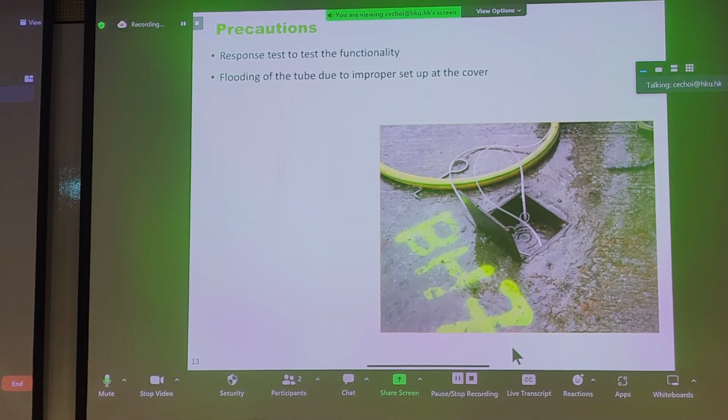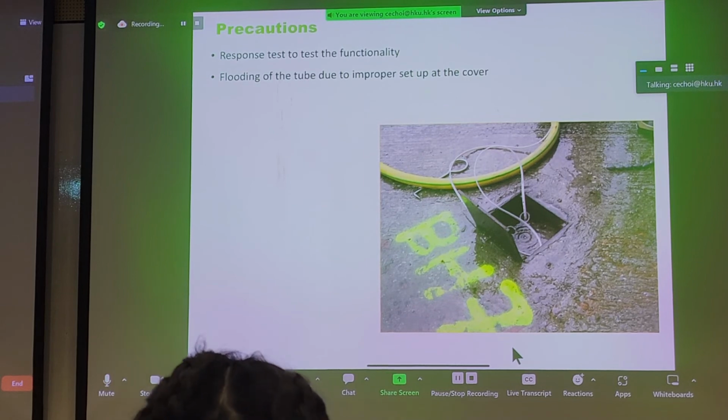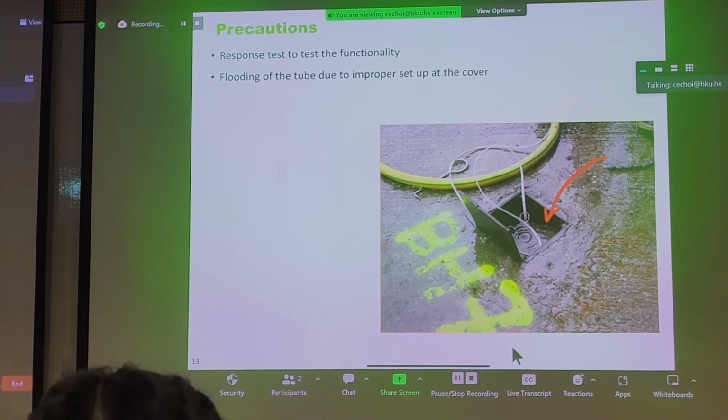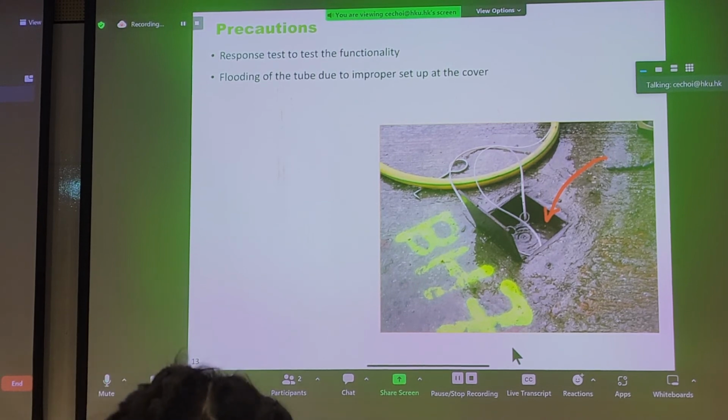So, some other salient points to worry about for standpipes and piezometers. You have to really trust the person taking the readings. More often, these are technicians that have measured a lot of standpipes and piezometers over time, and some of these readings could be influenced by runoff into the top of your pipes, and this can give you very misleading readings. So this is one thing to be aware of. That's why we seal the top and we have covers to minimize the effects of surface runoff on our readings. So this is just one precaution to bear in mind.